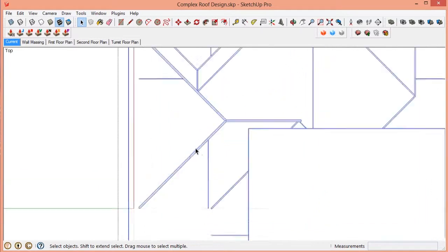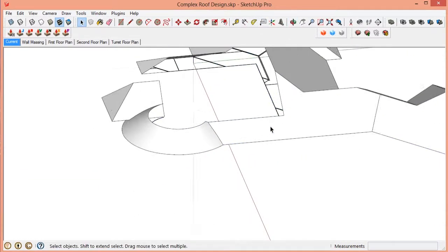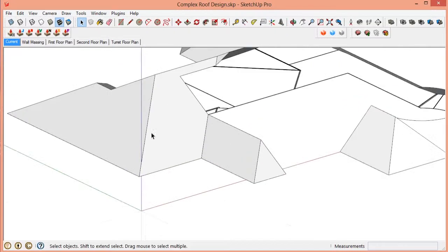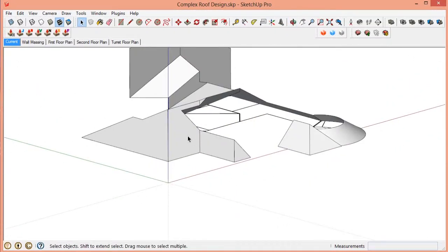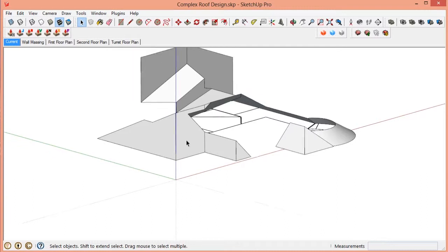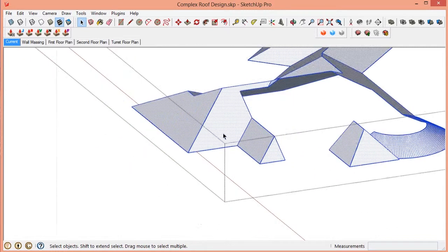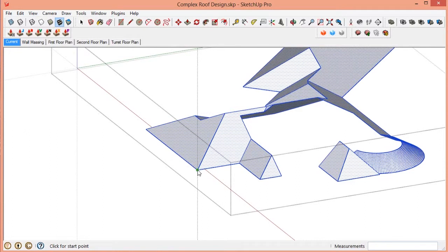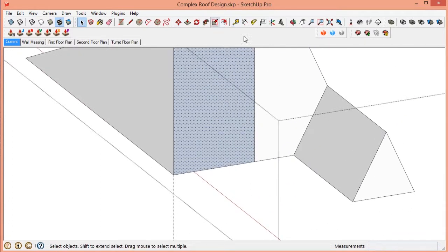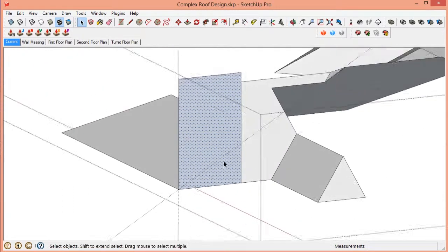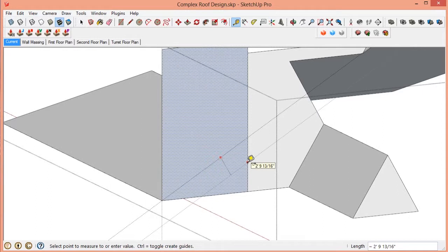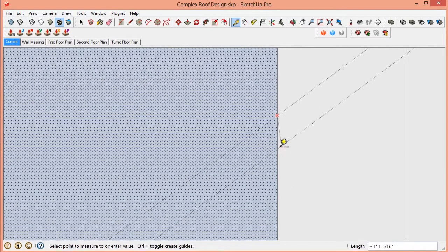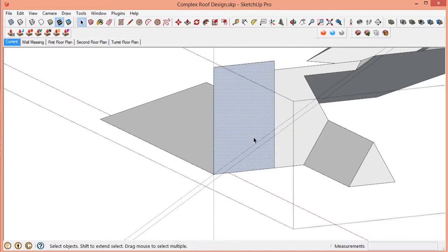Now that we have a 2D representation of our skeleton, we'll need to extrude it into 3D. To do that, we'll need to determine what the plumb dimension is of our common framing members, or perhaps our largest framing members. I believe we'll be using 2x12s, for example, for the common rafters, and so we will create a plane here that we can set up our 7/12 pitch, then copy this guideline 11.5 inches parallel, which will then determine our plumb dimension.